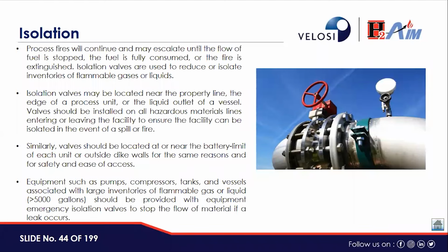Similarly, valves should be located at or near the battery limit of each unit or outside dike walls for the same reasons and for safety and ease of access. Equipment such as pumps, compressors, tanks, and vessels associated with large inventories of flammable gas or liquids should be provided with equipment emergency isolation valves to stop the flow of material if a leak occurs.